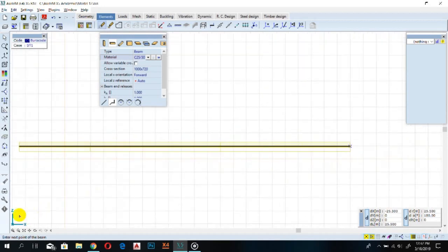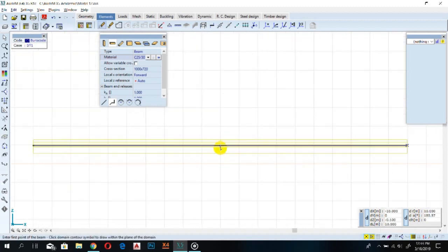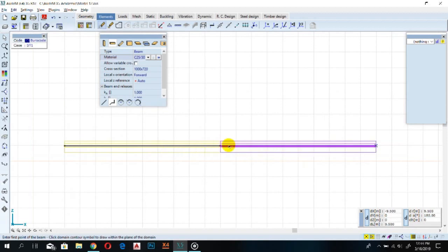Otherwise, we are in this Z and X coordinate. You can just press Z. I will show you how. Just press the Z key from the keyboard and just type like 5 meter. I'll click OK. So now I have gotten this in the Z axis, but I don't want it in the Z axis. Sorry, I pressed the Z, that's why, then I just undo and everything is erased, but I will do it again for you, and that's fine. Yeah, okay, you can use the shortcuts to draw it automatically and fast.